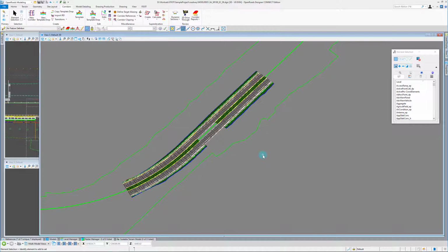So kind of going back to the beginning of this video, you can see how important it is to have a model plan, to appropriately name your files, to appropriately name your corridors, and have all your templates lining up with appropriate names. And if you have a model plan and you've taken appropriate notes, it's something that you can turn in when you get your model 3D reviewed, so the reviewer can go through your plan and easily follow what you've been doing. I think it'll allow us to have much better reviews and really give our reviewers a much easier time. So that's all for this video.